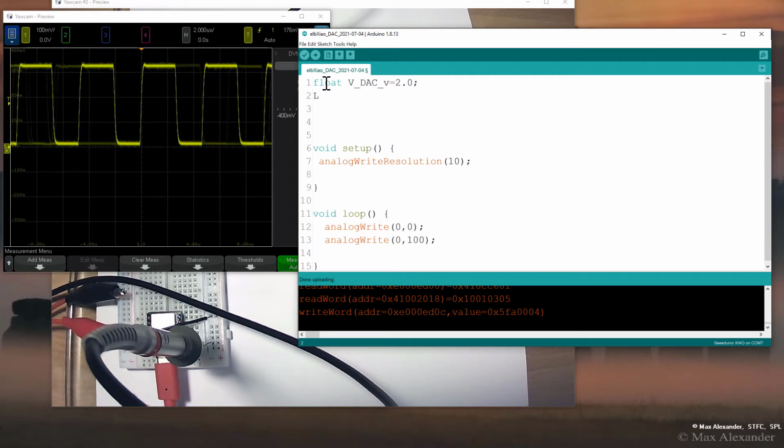So I'm going to use a long. I'm going to use the same variable, DAC, but this is going to be in units of ADUs, analog to digital units. This is going to be the integer. And that's going to equal the voltage of the DAC that I want to have coming out, in volts. That's the value I want. And I have to scale that. I have to divide that by, remember our full scale is 0 to 1023. And it's supposed to be 0 to 3.3 volts is mapped into 0 to 1023. And so I want to divide this by the maximum voltage.